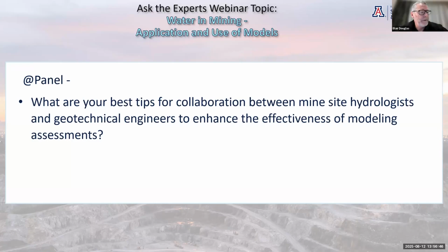Sorry, Christian. I think the one thing to add to the discussion is make sure you align your data sets to the type of sections of geotechnical analysis. If the geotechnical analyses are in 2D sections, make sure you study those sections and you understand them, and that you understand as a hydrogeologist, and vice versa, what's the sensitivity of pressures in this area and what's the uncertainty of that sensitivity.